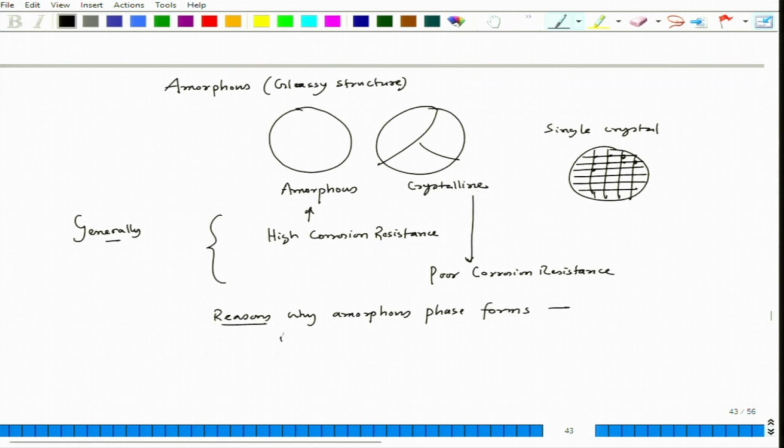Okay. So, one is multi-component. If we consider the metallic state, that time we call it metallic glass. The multi-component alloy composition should be chosen in such a fashion that there is competition between crystalline phases. Let us say A, B, C, 3 component elements are there. Let us say AB crystal tries to form and BC crystal is trying to form.